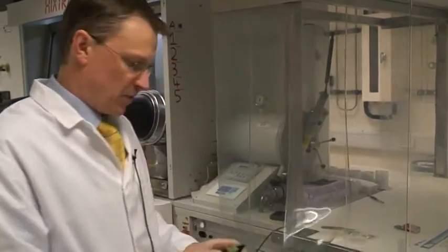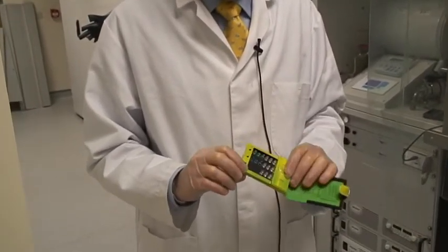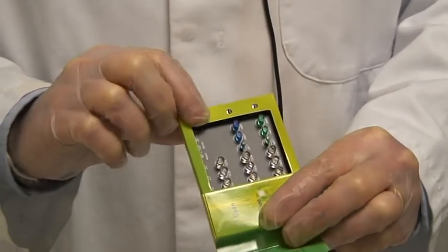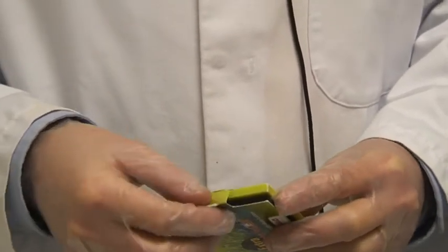Initially, the first application is for optoelectronic devices, and these are some commercial LEDs, light-emitting diodes, that are manufactured from gallium nitride, emitting in the blue and the green. There's additional ones in between, and it's cyan. You can use gallium nitride to grow any colour of LED, from the ultraviolet through to the green. People also would like to try to achieve better quality yellow light, although that is very challenging due to the amount of indium that is to be put in. This is a key area of research that we wish to examine at Tyndall.